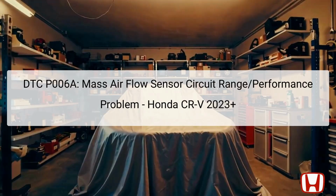The Diagnostic Trouble Code, DTC P006A, indicates a mass airflow (MAF) sensor circuit range performance problem in the Honda CR-V 2023 and onwards. This DTC is triggered when there is a discrepancy between the intake air volume measured by the MAF sensor and the assumed intake air volume calculated based on the Manifold Absolute Pressure (MAP) sensor output. The Powertrain Control Module (PCM) monitors these values, and if they fall outside a specified range, it recognizes an anomaly